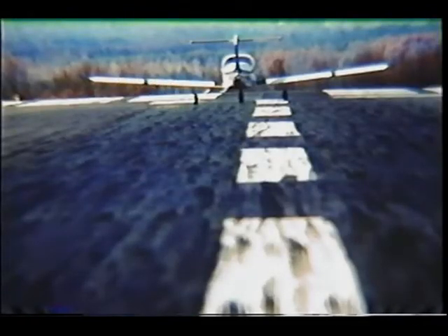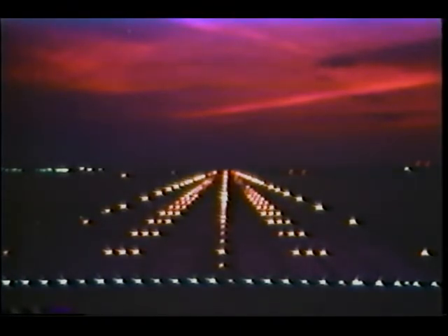Getting back to operating procedures, though, let me test you with this one. You should always stay right smack dab on the runway center line during your landing rollout. True or false? Well, it's false. At airports equipped with centerline in-runway lighting, it's actually best to keep your nose gear a few inches to the left or right to avoid excessive wear and tear, as well as possible nose gear damage. But at all other airports, it is best to stay right on the runway centerline.